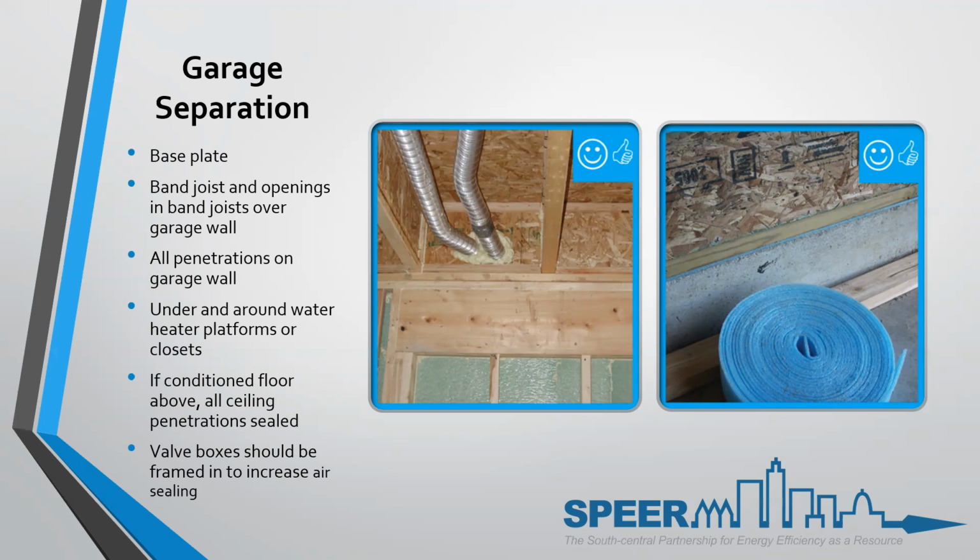However, if the walls of that garage are not attached to living spaces, then none of this really matters, except the gasket underneath it should be a moisture stop. But if you're talking about energy, it doesn't call out moisture stops. That's the IRC calling out, saying it needs to have it underneath it. It probably by building code should have it, but it has nothing to do with air sealing. So that's a great question.